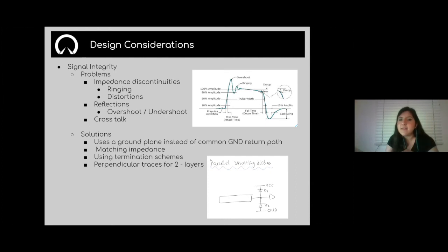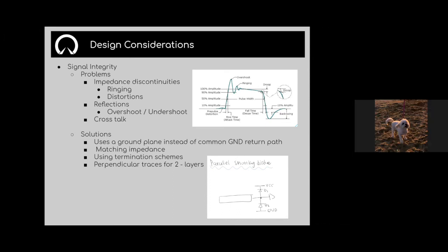And so what that does essentially is that it adds this extra voltage to your square pulse. And you could see that there with the overshoot, that's the extra voltage that's going on. And you could also get undershoot, which is just excess negative voltage in the opposite direction. So that's pretty much overshoot and undershoot. But the square wave should be the ideal signal, not the excess one. That makes sense.